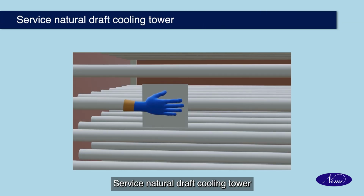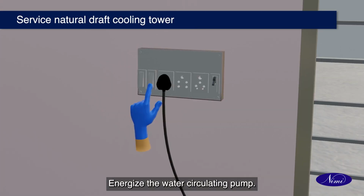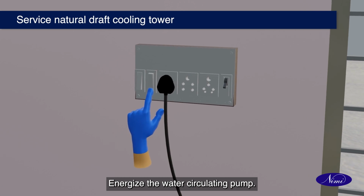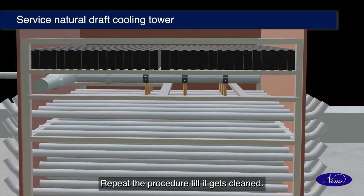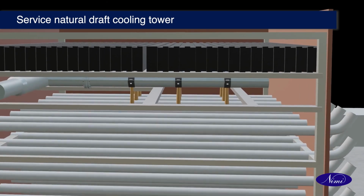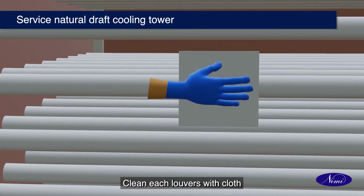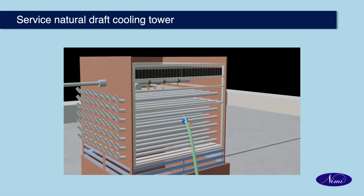Service natural draft cooling tower. Check the water spray. Open the inlet and outlet valve. Energize the water circulating pump. Observe the water spray through nozzles. Repeat the procedure till it gets cleaned. Clean each louvers with cloth. Clean the spray nozzles. Clean the louvers.